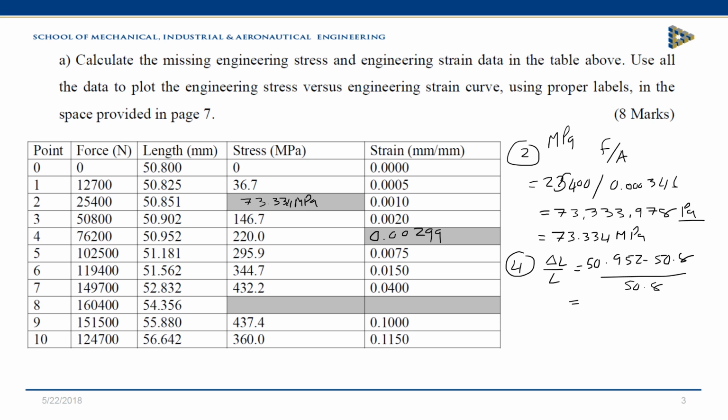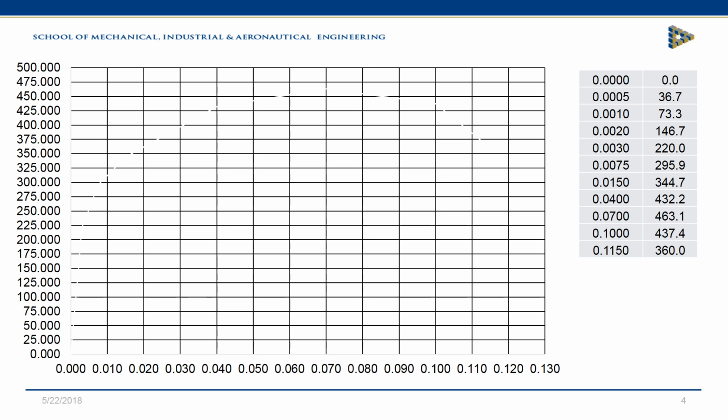Then using the same method, I calculate the stress as 463.101 MPa, and I calculate the strain as 0.0700. Okay, so that's the first part of the question. I probably would have gotten about 4 marks for that, for 4 calculations.